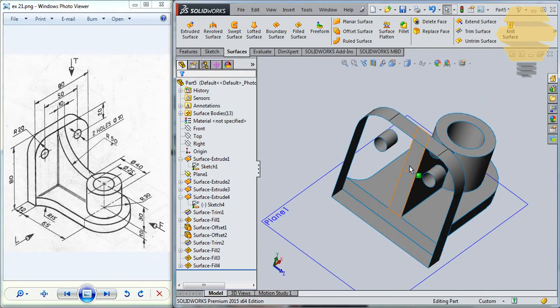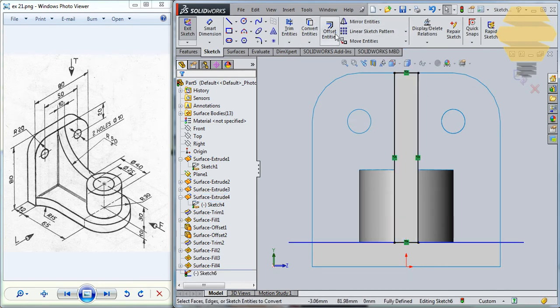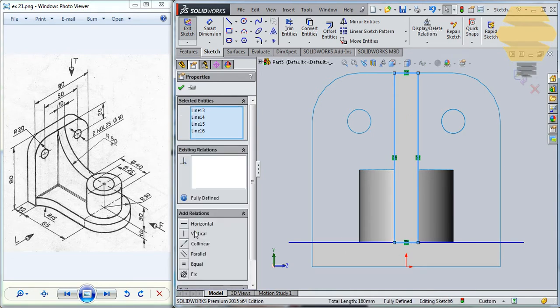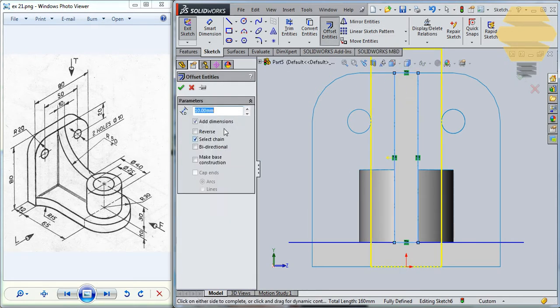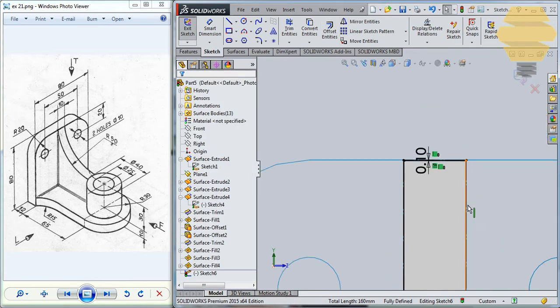Now you gotta open this. So to open that, go for sketch. You can go for convert entities, and that's converted. Select those 4 lines and convert them for construction. Now what we can do is go for offset and offset it with 0.1 in the reverse direction. You can just see that the new lines should be coming inside. Now we have that created, right?